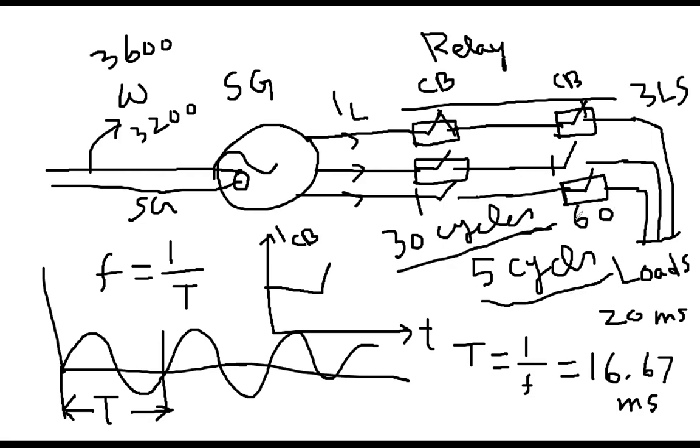So everybody, could you follow me on what I am saying? First, I said that when the fault happened, within 5 cycles, this breaker will open. And then I am assuming that the fault got cleared and disappeared. Again, you need to reconnect the breaker. That reconnecting time, after opening the breaker, is another 30 to 60 cycles. That is the duration. Some waiting time is needed.